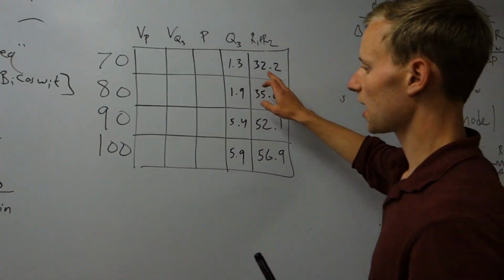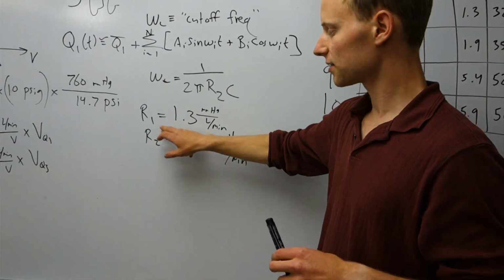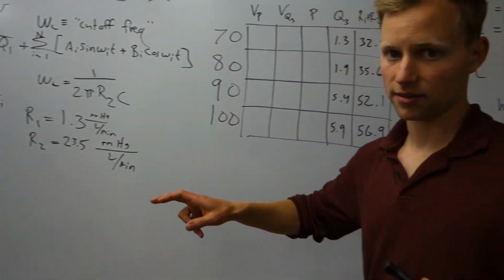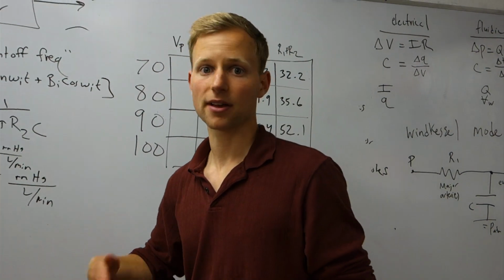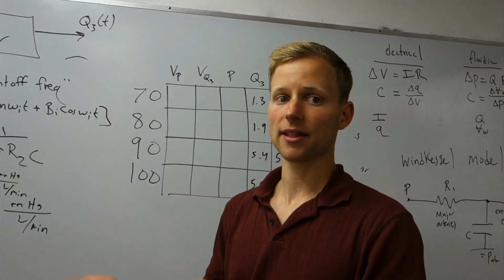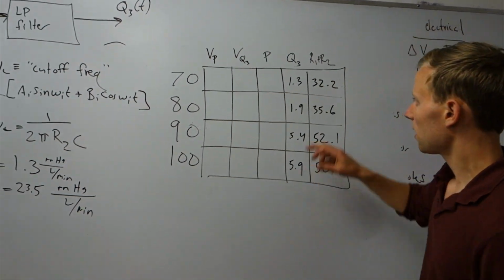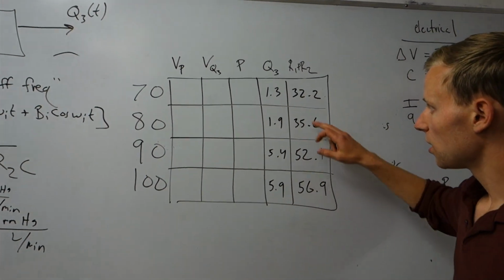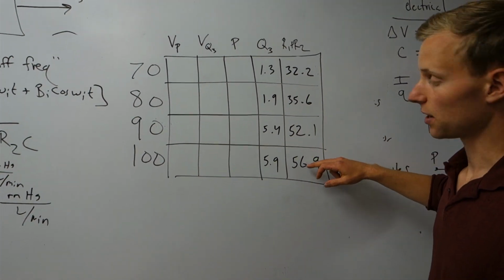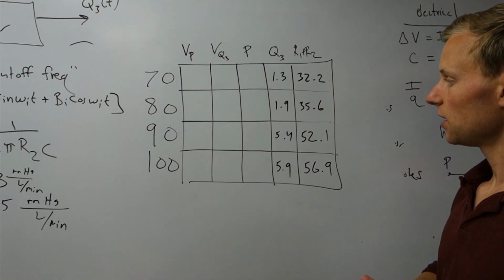So there's something that we're not taking into account using these R1 plus R2 values, and that would just be the head loss due to the flow through the pipe, the viscous losses in the pipe, and the minor and major head losses of the bends and the expansions and the contractions and whatnot. Now, why aren't these constant values? This should be constant if it's all laminar. Well, it's not laminar for one reason.